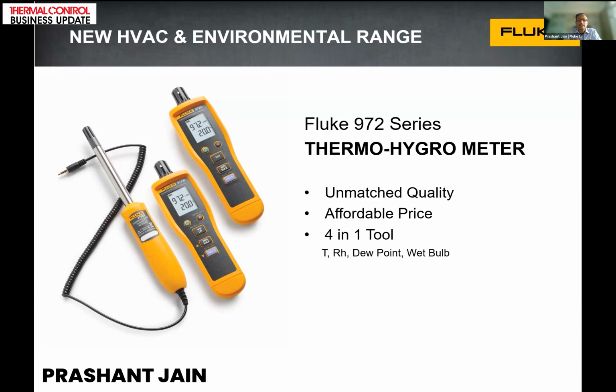So it helps us as a cross check, and it gives us the flexibility to measure multiple points, in fact infinite points inside our building, because we can easily walk around with these sensors in our hand. Generally the quality and the reliability of these sensors are very high compared to the fixed ones, and these are easy to calibrate. So there are some benefits of continuous data monitoring, I cannot discount that, but at the same time spot testing or handheld instruments have their own advantages in terms of flexibility, where to monitor, as well as the easy calibration side.